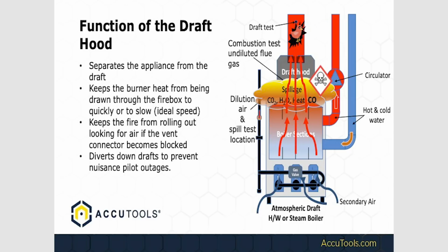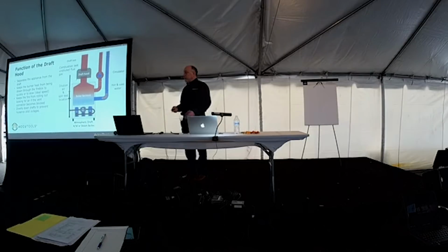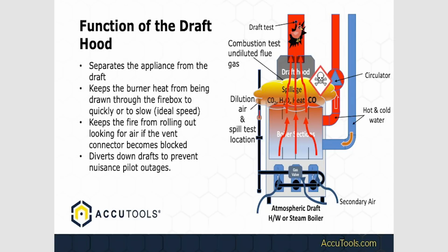If you go back and look at why appliances were built the way they were built, and why we have an electrical code, it's because of fires. Everything was catching on fire back in the day. I mean, it was pretty darn common. So if we separated the appliance from the draft, and the chimney became blocked, then the flue gas could come out and spill into the space, and the carbon dioxide, water vapor, and heat was a lot safer than a fire. Because the odds are that as long as the boiler is burning correctly, you'd just realize you had high humidity in your house. A lot of people don't realize that if you walk into a home and they complain about high humidity all the time, you better start looking at the large appliances for dumping flue gases into the home.